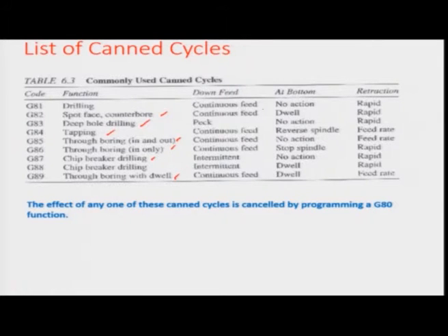So, you have different down feeds in all these certain action points, which are what happens to the final depth where the tool reaches, and then certain points related to how the tool has to be retracted, okay. And then these codes are accordingly designed in a manner so that every time this challenge is faced, for designing a CNC code, you just simply put the command and it executes a sequence of events just like the drilling, okay, where only this value specification or specified value in a block would suffice for the whole operation to take place.